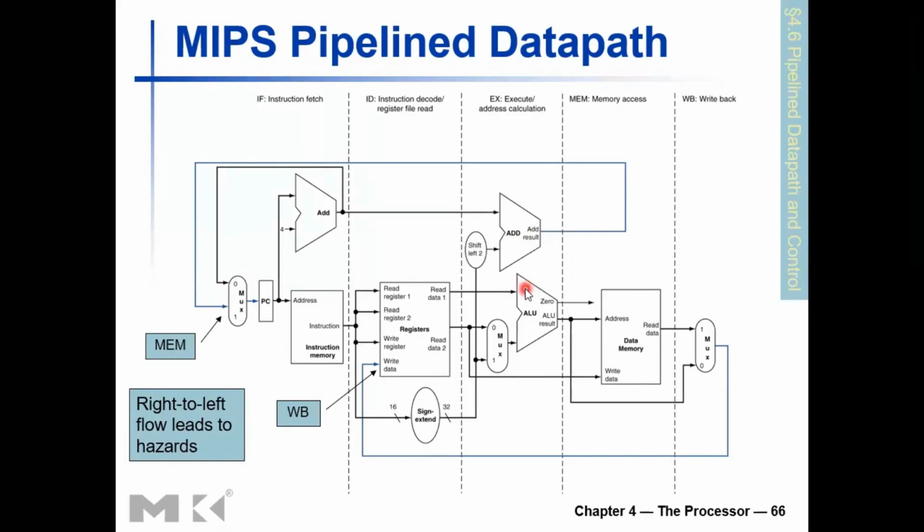As we discussed when we discussed the control hazards, if you want to avoid the stalls introduced by having branches, then you would need to have an additional adder circuitry inside this instruction decode stage after the register reading to compute the branch condition outside the ALU in the earlier stage, and move the branch target computation hardware also into the register decode, instruction decode and register reading stage, which would make that stage slower than usual.